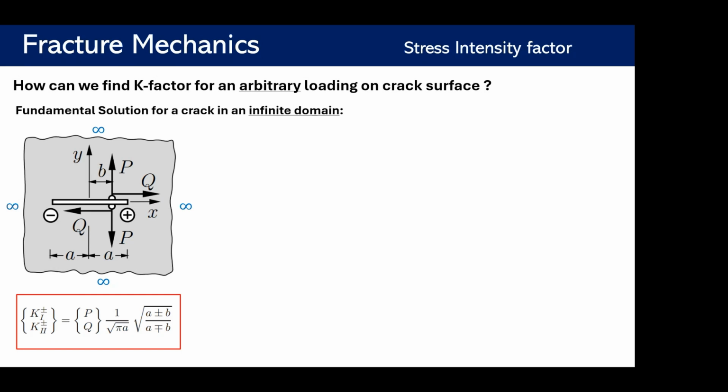Okay, imagine this problem and just focus on the P, not Q. P on this fracture generates the first mode, and Q generates the second mode, shear stress. So just focus on the P. So we have a fracture. The fracture has a specific length of 2A.